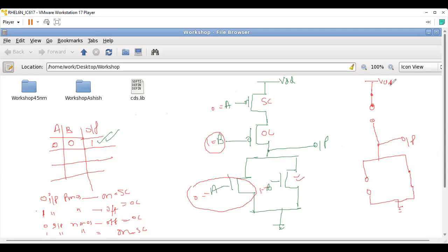Now you see this VDD do not have any path to reach to output. And if there is anything on this output, this will go through this path towards ground. So finally, the output will have a 0. Wherever the total current flows towards the ground, it clearly means that you have nothing in the output. Got the point, everyone?